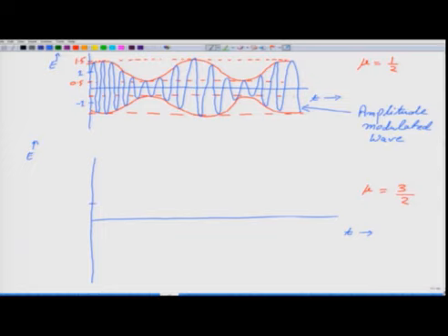So the amplitude of the carrier wave is 1, and of course on the negative side it goes to -1, and the amplitude of the modulating wave, our signal wave, is 1.5 times bigger than this. So the maxima will now go to 2.5, on the negative side also it will be at -2.5, and the minimum of this amplitude modulated wave, since we have considered its amplitude as 1.5, will go to -0.5 and similarly to +0.5.